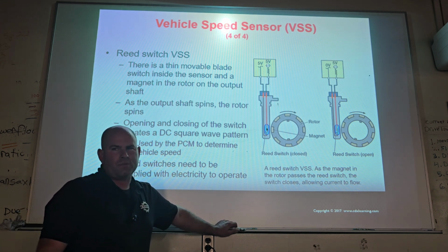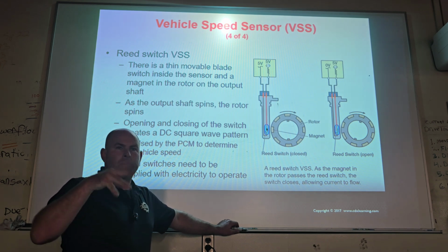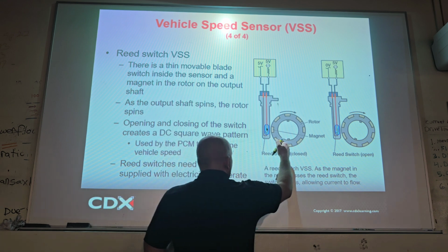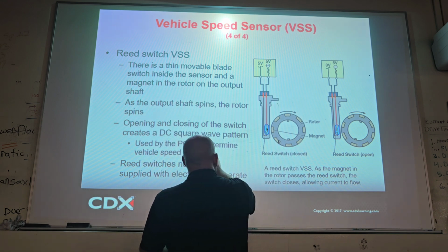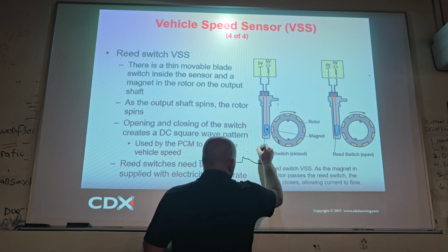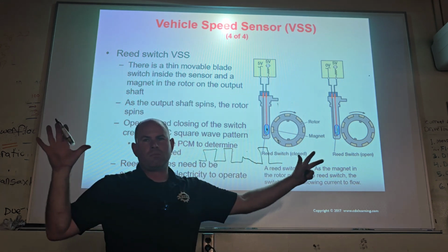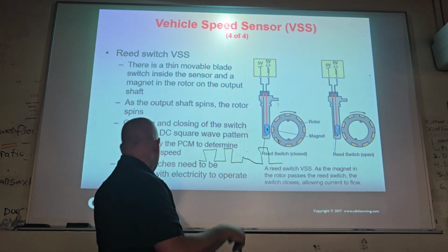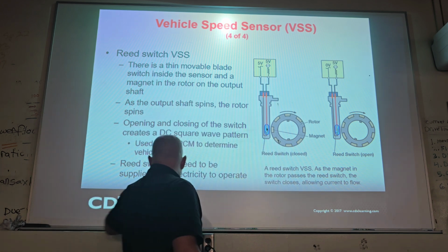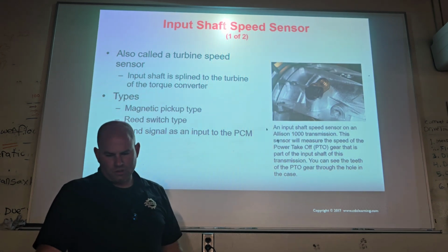This one, again, you could try to use your meter. Some of the meters, like a nice Fluke, will have an RPM function, and it'll give you a number, and as you speed up, that number will go up. But if you had a damaged magnet right here, on the waveform, that might look like this, right? So you could see that on a picoscope. On your meter, you'll miss it. You'll be like, I have no idea what's wrong with this. When you put a scope on it, you'll be like, oh, I see that. That magnet in there is broken or something. Okay, so that's again why I'm plugging for the picoscope or some sort of oscilloscope.